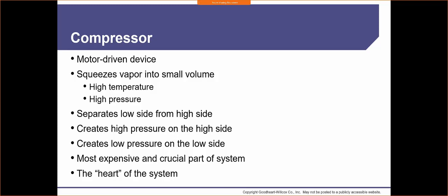Okay. So if we do have a compressor that does fail, there's a lot of work that's involved as far as replacing it. Sometimes it's just much easier to replace the entire condenser rather than deal with replacing just the compressor. In larger commercial settings, that's not really an option, so you will replace the compressor. And they are heavy, so just keep that in mind. We're talking about 100, 150 pounds a piece on average just for residential units.